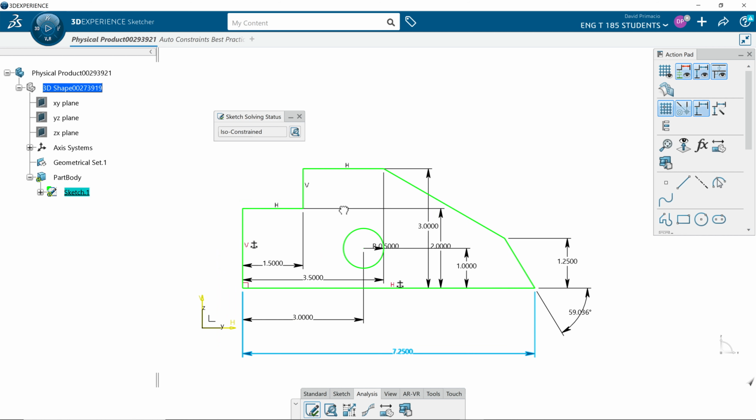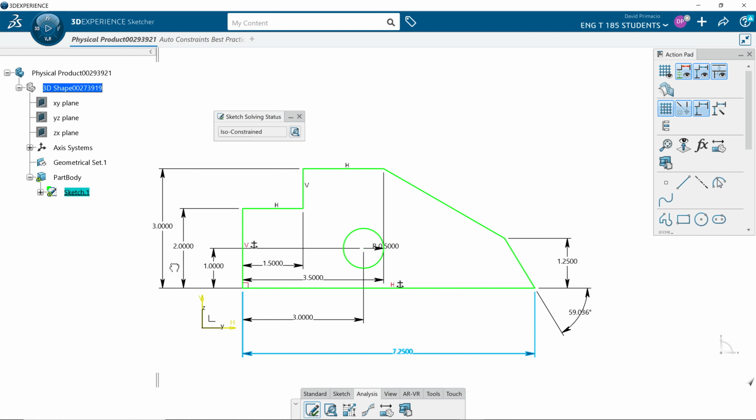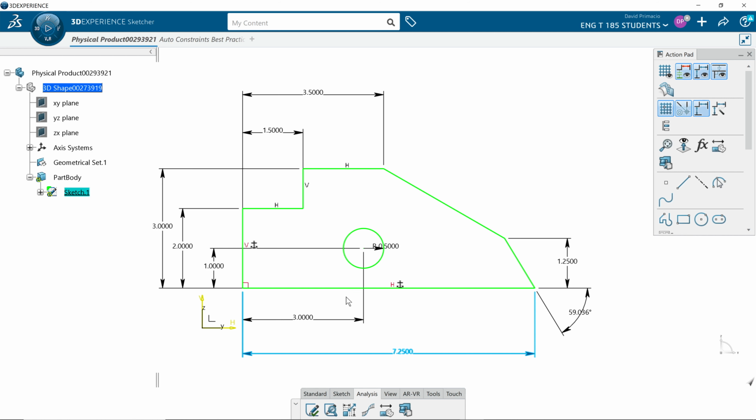This dimension here is correct. I should start from the inside out. And you want to move this out as if you're doing a drawing. So you're going to grab these dimensions and move them off. And then all I would have to do, again, is edit the value to match the drawing. Should have grabbed that one first. Okay. I'll move this one just off there. On a drawing, this has to be off the part. You could leave it here on the sketch.